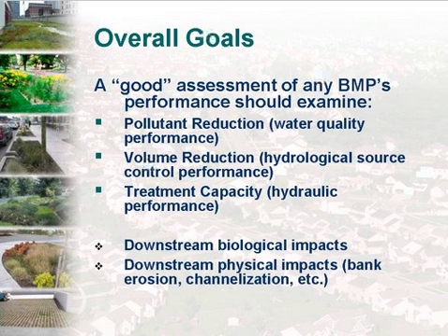That is, how is it performing from a treatment capacity standpoint? One very important aspect of BMP performance together is the amount of flow that actually bypasses the BMP during rainfall events that are larger than the design event, for instance. And, John, that would be particularly important for some of these new class of BMPs, these low-impact development techniques such as bioretention cells. Yes. We do want to have a better handle on how much they will infiltrate and what size of a cell is going to handle what storm event and that sort of stuff. And that's one of those things that's hard to nail down right now, would you say?